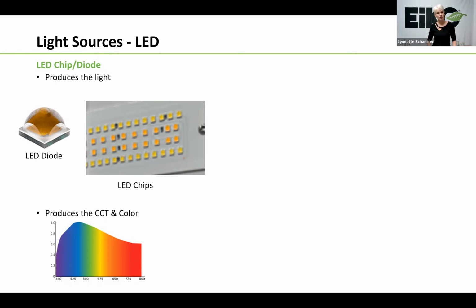Now, manufacturers use different colors of LEDs and different materials of semiconductors to control the energy level to produce the light color and to produce the light. The color of light that comes from these semiconductors really just depends on the specific semiconductor material that's used. It also depends on the current that's being supplied to the LED chips. The point is that most manufacturers do not use a colored lens. They used to at one point, but not anymore. Most of it's all done right on the chip itself and through the semiconductors. But anyways, that's the biggest thing that I wanted you to take away from that.